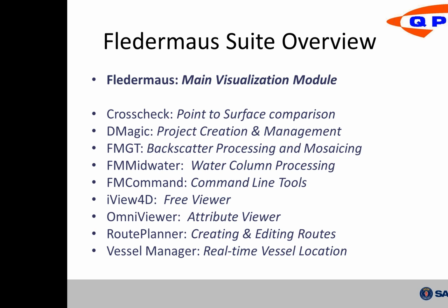It's a good way if you have a file and you're not sure what's going wrong when you're trying to import it. A good tip is just to open up an OmniViewer, and if you can't read it in OmniViewer and you're not seeing good values, well, something is not working along the chain. Either there's a corruption in the file, or we're not being able to read that file properly.